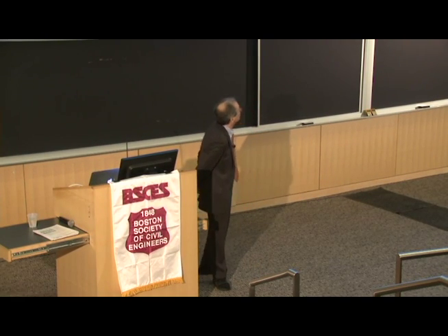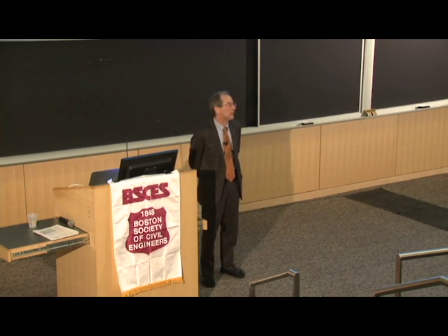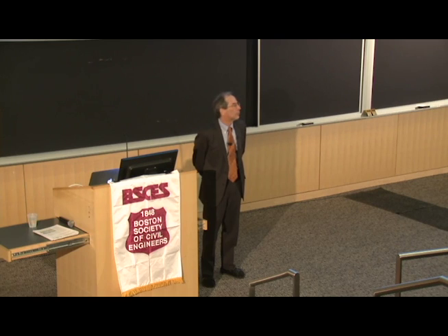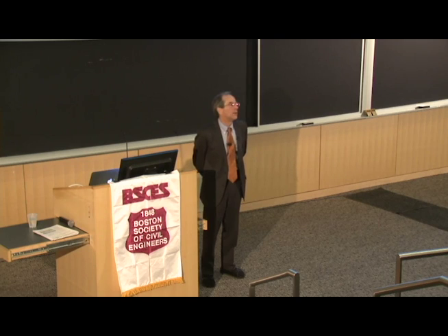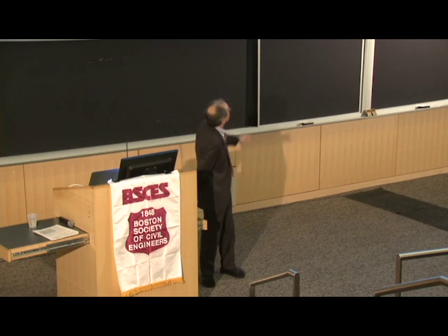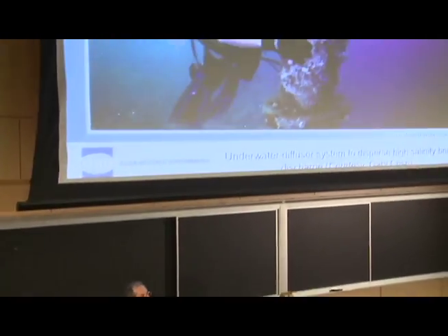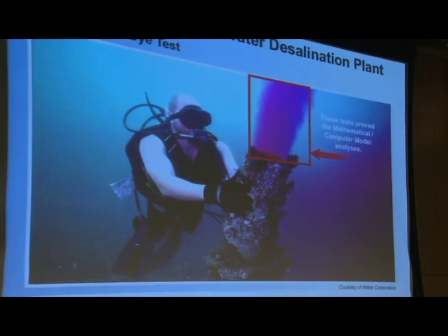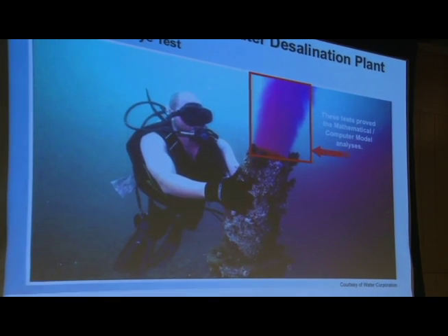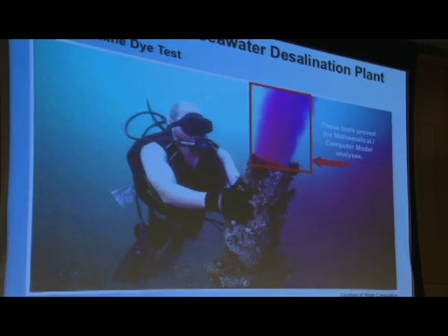The plants in Perth were built in an area that had a sensitive marine ecosystem and a lot of environmental regulation to protect it. So in this case, what they did was to build an outfall pipeline that went a couple kilometers offshore, and they have a 6-acre site where they've got about 20 nozzles like this one distributed at spacings of 20 meters or so. Water is injected with some velocity, as you can see here. They rely on turbulent mixing to diffuse it and to ensure that the salinity decreases to within a couple parts per thousand of background within about 100 meters.